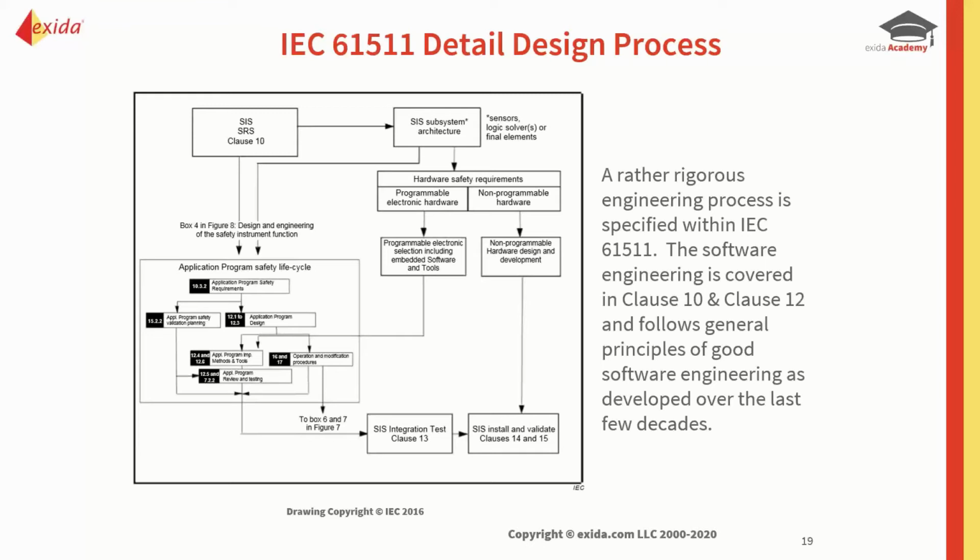So we have to do verification of each of the modules, and then eventually, as I said, during FAT, we would do the validation of the application program as a whole with the logic solver. And I'm sure quite a few of you have been in factory acceptance tests, FATs.